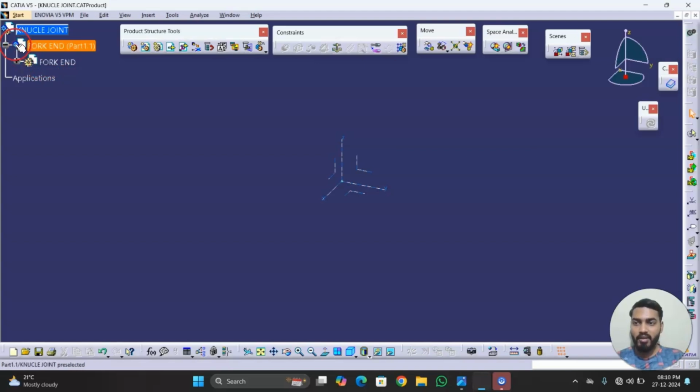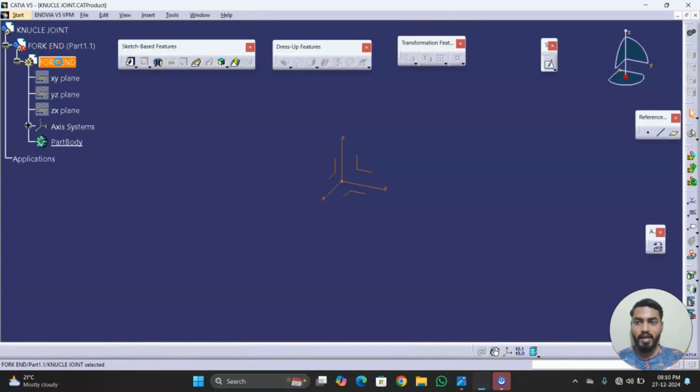If we have two gears with this axis system and with this blank sheet, this is nothing but a part inserted into assembly design. If we have two gears with a blank sheet, that we call an assembly design. Now this is the part, we just need to double click on this single gear option, then directly it will reflect back to part design.